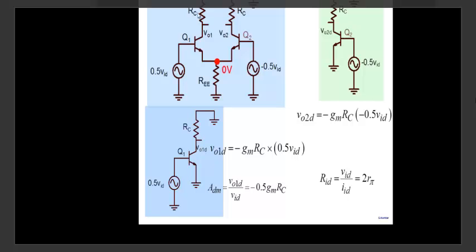Okay, so even in this case, if RC1 is different from RC2, it's a fairly good assumption that you make it equal to ground. Okay, so in differential mode, you make this equal to small signal ground, and the results are going to be fairly accurate. Even to the extreme, let's say I have an RC here and I don't put any RC here. I take this node and I put it directly to ground. I don't even have an RC here. Even then you'll find that this point is reasonably small signal ground. Okay, so you can make those assumptions. And we saw in, yes.